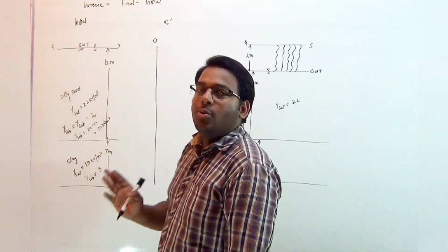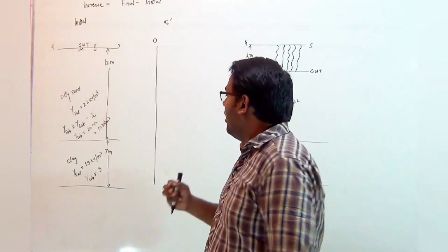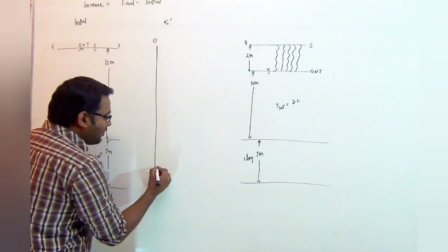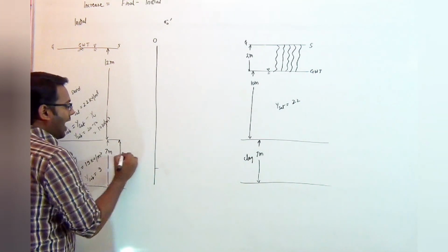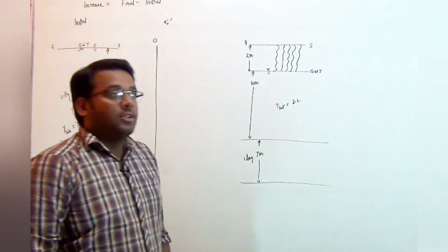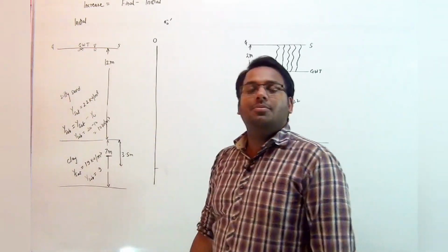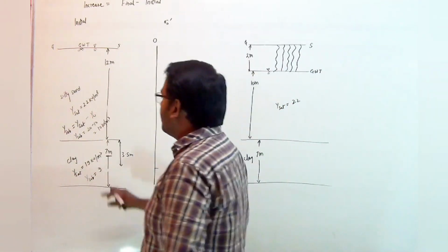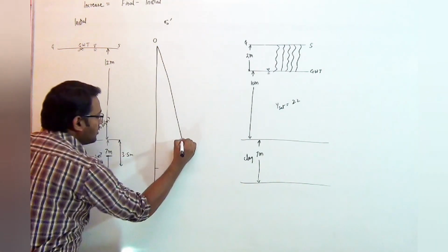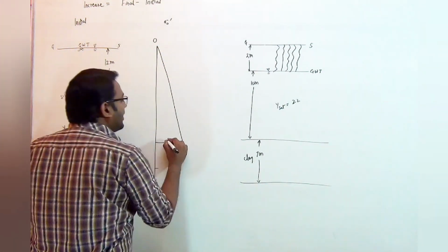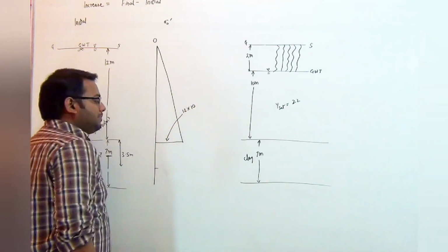We are required to calculate the increase at the mid depth of the clay. So we are plotting the diagram till the mid depth, and the mid depth will be at a distance of 3.5 meters, that is half of 7 meter. So now to start, for the first 12 meter, gamma submerged of the silty sand will be used, and gamma submerged for the silty sand is 10. So for the first 12 meter, it will increase at a rate of gamma submerged, that is 10.